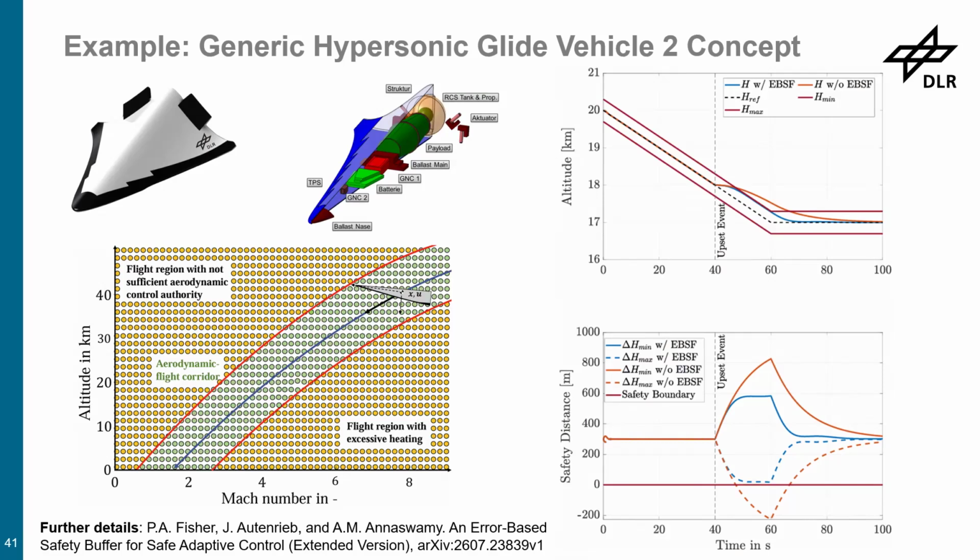But normally, when you have a hypersonic glide vehicle or reentry vehicle, you have an aerodynamic corridor in which you have to stay, right? If you are too high, the density is not high enough, so you have thin air and you will lose aerodynamic controllability. And if you are too low, then you have a very high Mach number and high density atmospheric layers, and you could experience high heat fluxes and high heat loads. So you have to prevent that as well.